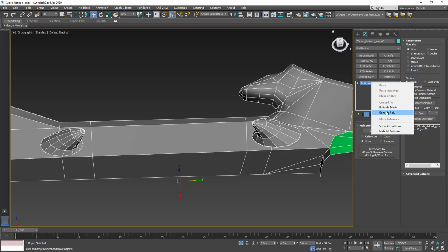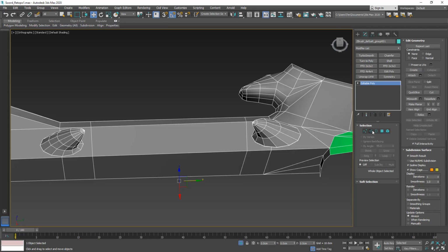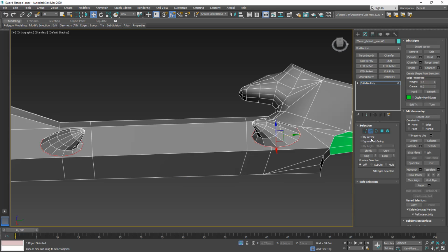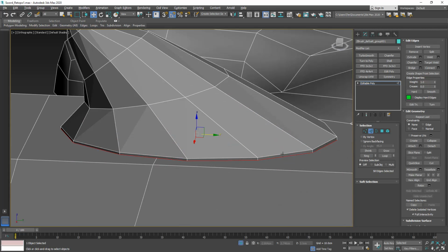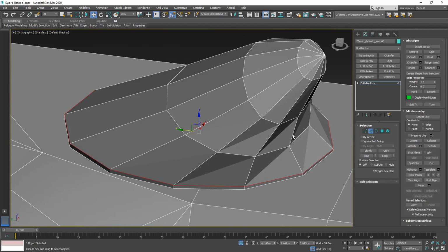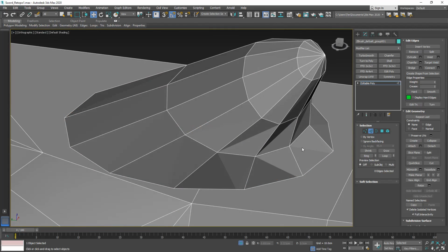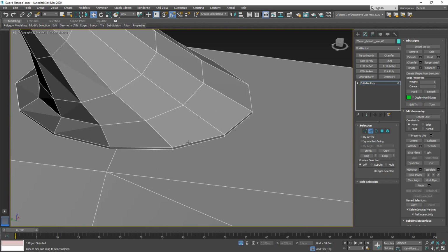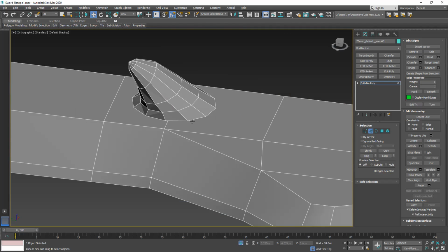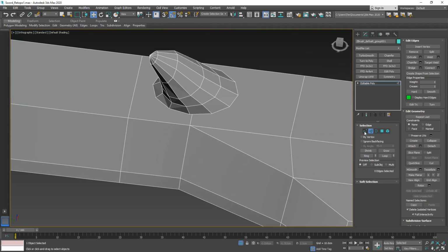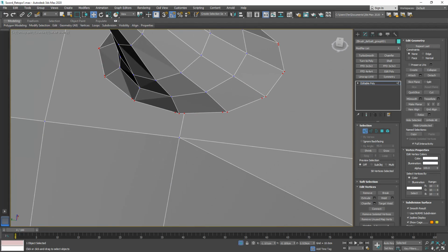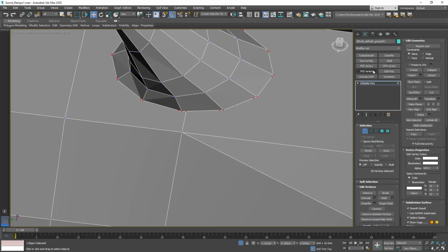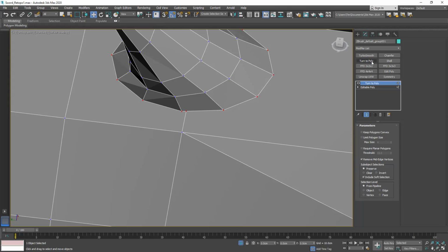But now let's right click it here, go back to our editable poly mode, go into edge mode, zoom in here, and then this loop here we can just Ctrl and backspace it. So here we have to do the same thing, Ctrl backspace on this loop. And now if we go to vertex mode, you can see that through that Boolean operation, we have some extra vertices. And we want to use our turn to poly modifier here, which magically gets rid of it.